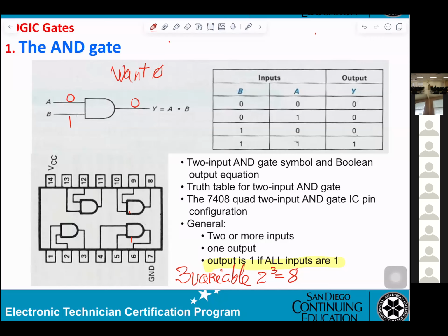When you measure the output, it is not 0. You can get 1.5 volt. 1.5 volt is not a logic level you want. They can be either higher than 2.8 volt, or less than 0.8 volt. They have to be either 0 or 1.